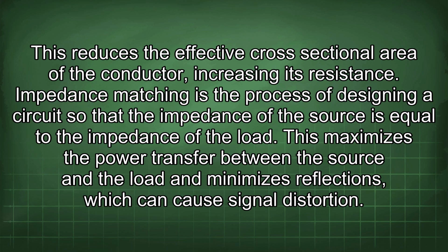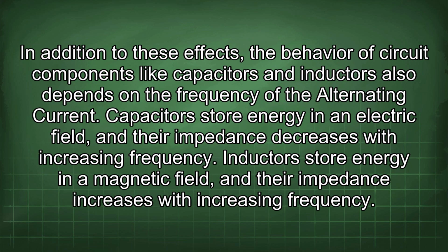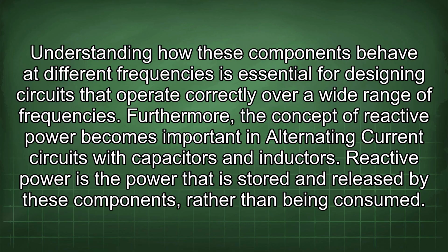In addition to these effects, the behavior of circuit components like capacitors and inductors also depends on the frequency of the alternating current. Capacitors store energy in an electric field, and their impedance decreases with increasing frequency. Inductors store energy in a magnetic field, and their impedance increases with increasing frequency. Understanding how these components behave at different frequencies is essential for designing circuits that operate correctly over a wide range of frequencies. Furthermore, the concept of reactive power becomes important in alternating current circuits with capacitors and inductors.